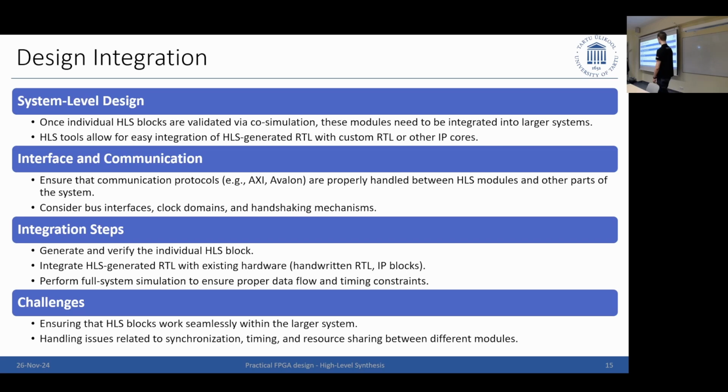Design integration. Yes. Oh yeah, so basically, there was this one: HLS sounds like a tool which you could use for your full FPGA design. You can, especially if you work with system on chips. Then you basically will potentially never leave your HLS, and you write your C processor code, and at the same time, this one I want to have running on my FPGA, and you write it almost in the same way. In the same tool, very convenient, so you don't even notice anymore where is what.